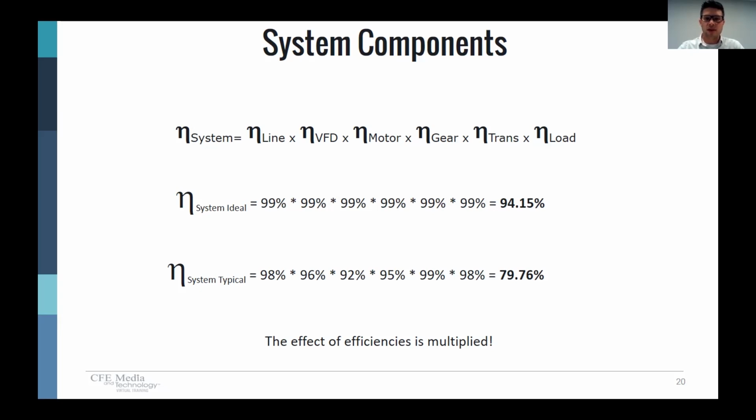But one of the things you can think about is eliminating some of those components in between. Maybe you don't need a transmission element. Maybe you don't need a belt to couple the gearbox to your conveyor. If we get rid of one of those elements, you can get rid of some of the inefficiencies, and that would make your entire system a little bit more efficient.